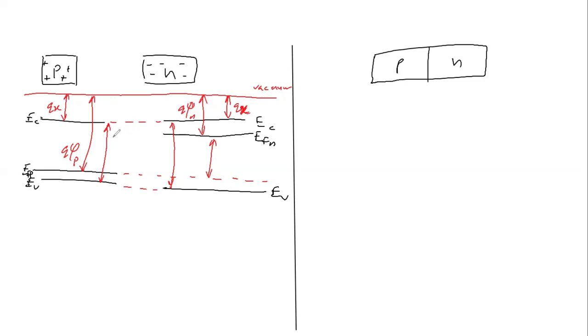Now, this is the energy band gap, which is the spacing between the conduction and the valence band, okay? So this is say Eg and is the same as this Eg, okay? And now this distance, therefore, will be the difference between the two work functions, okay? This work function minus this work function will give us this distance, okay?